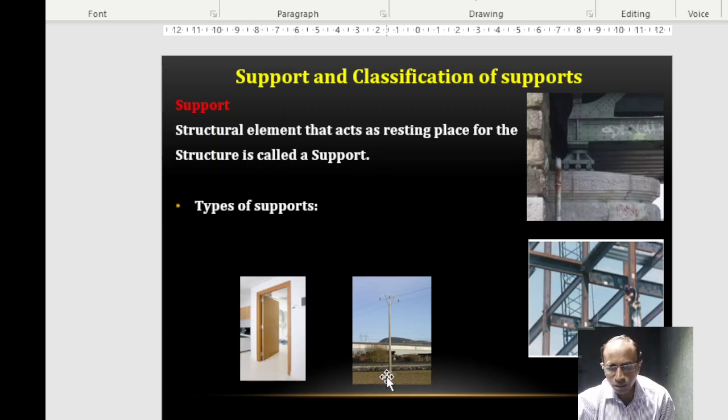And here it is fixed or clamped to the ground, right? Or here the stanchion column member and beam members are attached together. They made it as one unit by using the welding process or bolting or riveting. So this kind of clamping or fixed condition is provided here, right? So three different support conditions.